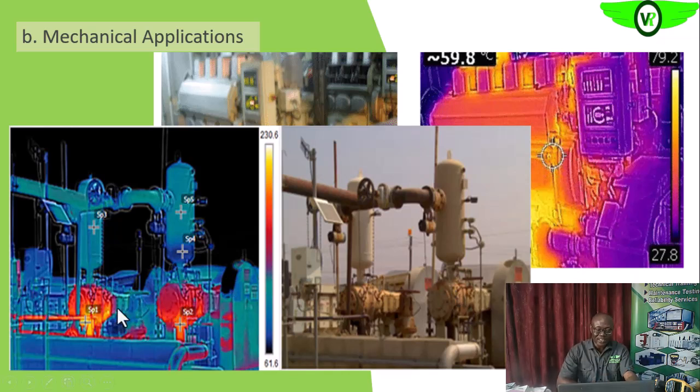So that increase in temperature is showing around these compressors before it is sent into, that could be an intercooler or a surge drum, can't say for sure, but it is cool here, which makes me suspect that it is an intercooler. So we have the cooling water lines coming into it.